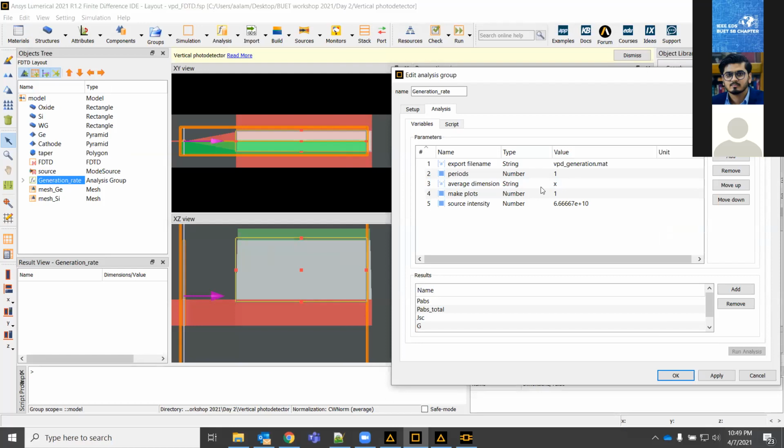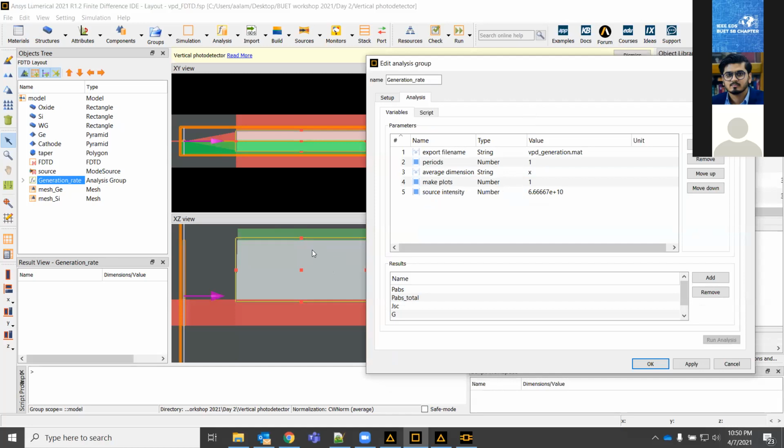When you do your charge simulation on a cross section, you can simply make the length in the third dimension equal to the length of this entire germanium. Then the current you end up with in your charge simulation will be close to the actual photocurrent you get from this detector. That's where the norm length that we saw in charge simulation comes into play.